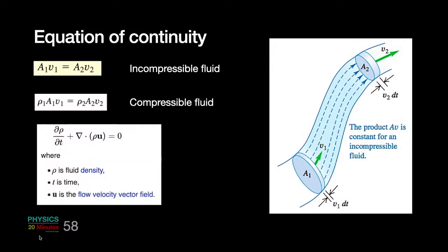I continue here and I present an equation. This is how the equation of continuity looks if your fluid is compressible and if you use a bit of vector calculus. What it says is del dot rho u, where u is the flow velocity, a vector field. It's a dot product, remember this is a vector del, and rho is the density. And if the density fluctuates, then the density fluctuation is d rho by dt. Remember this is a divergence. The divergence of rho times u is basically equal to the negative rate of change of density.